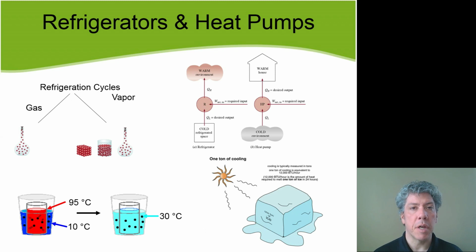However, water is not the most common fluid for refrigeration. Common fluids are refrigerants such as, well, ammonia in commercial systems. Ammonia is an excellent refrigerant. However, it is toxic, and so it's not used in small and residential environments where there can't be any significant control efforts to detect and mitigate for the toxicity of the ammonia and any hazardous releases. But it is commonly used in industry in large commercial installations.